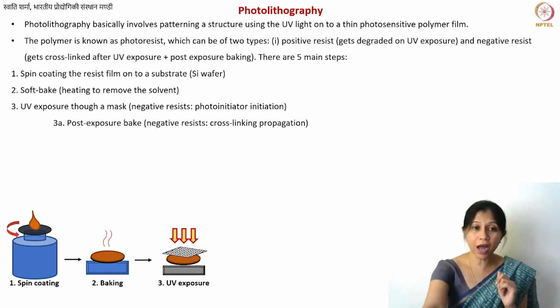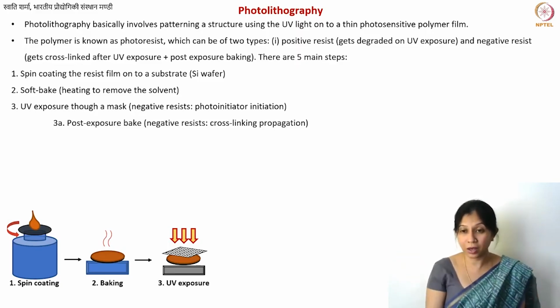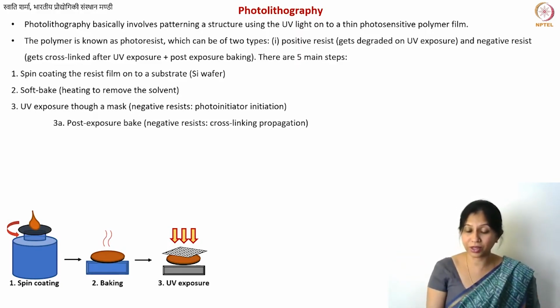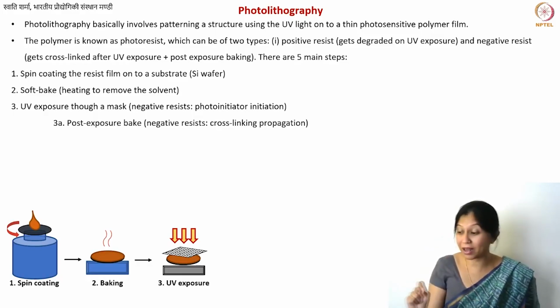Okay, now you did the UV exposure. Now will you have any dose of UV? No, the dose of UV light also you need to optimize, because now your material can cross-link when it is exposed to the UV light, or degrade also. Now if the film is too thick and I have not exposed it for long enough duration to the UV light, then maybe only the top part will get cross-linked.